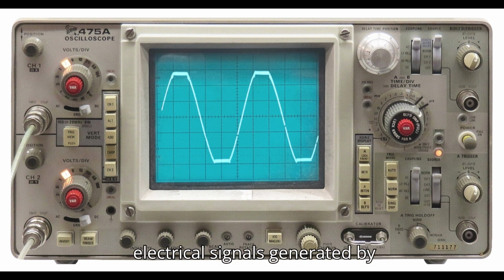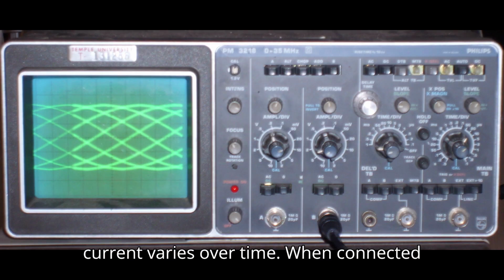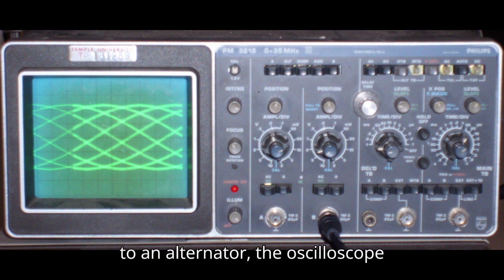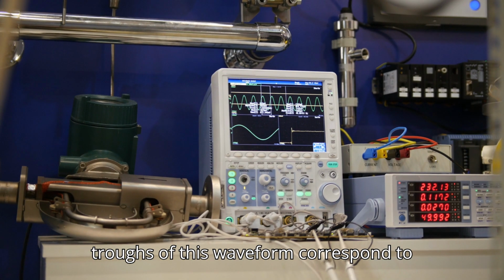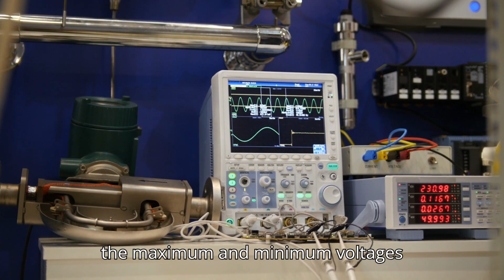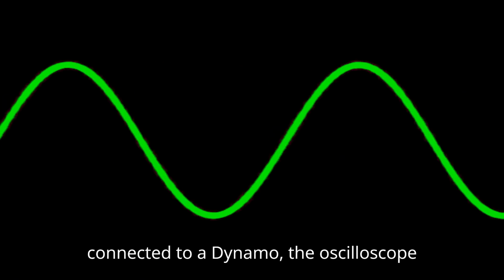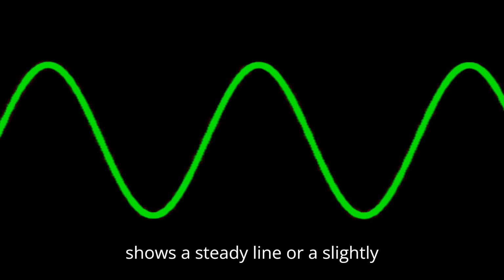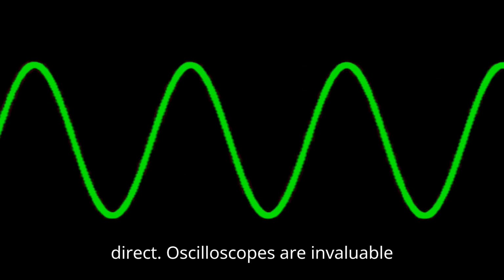To visualize the electrical signals generated by alternators and dynamos, an oscilloscope is often used. An oscilloscope is a device that graphically displays electrical signals, showing how voltage or current varies over time. When connected to an alternator, the oscilloscope displays a sinusoidal waveform, representing the alternating current's periodic rise and fall. The peaks and troughs of this waveform correspond to the maximum and minimum voltages generated as the rotor spins within the magnetic field. In contrast, when connected to a dynamo, the oscilloscope shows a steady line or a slightly pulsating waveform, indicating the continuous and unidirectional flow of direct current.